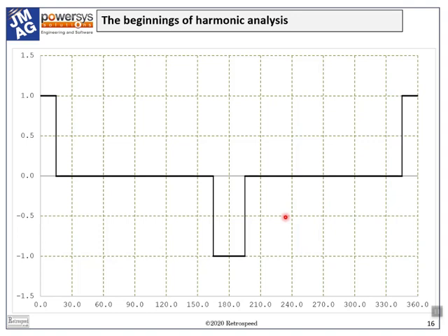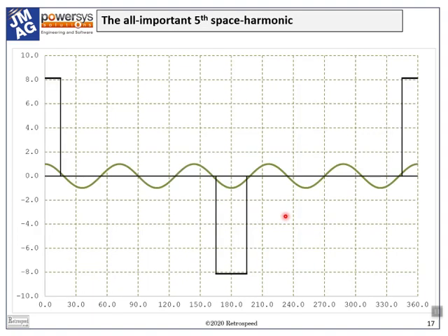And I've mentioned this many times, but the Fourier series should be used here and not the FFT. The Fourier series analysis gives us an infinite number of odd harmonics, and before we do anything else we want to pick out the fifth.